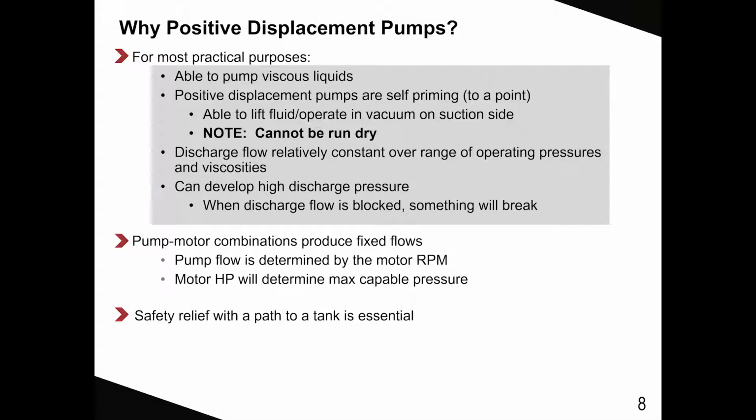And the other thing about positive displacement pumps is that per code in New York City and the international code, for fuel burning devices, you have to have positive displacement pumps.